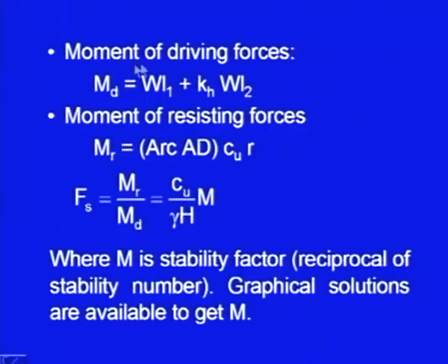So, moment of driving forces Md will be equal to W into L1, where L1 is the lever arm for weight and L2 is the lever arm for the force due to earthquake. So, W into L1 plus Kh into W into L2. The moment of the resisting forces will be the length of the arc along which these forces are acting, multiplied by Cu.